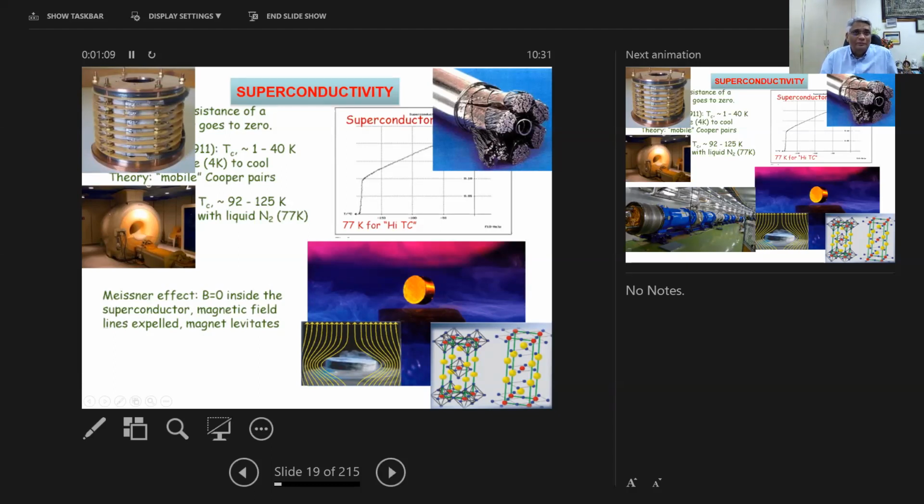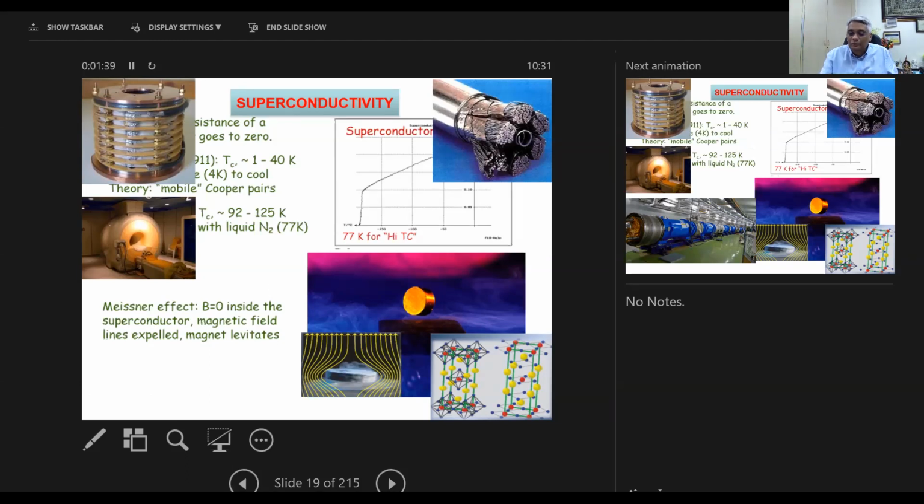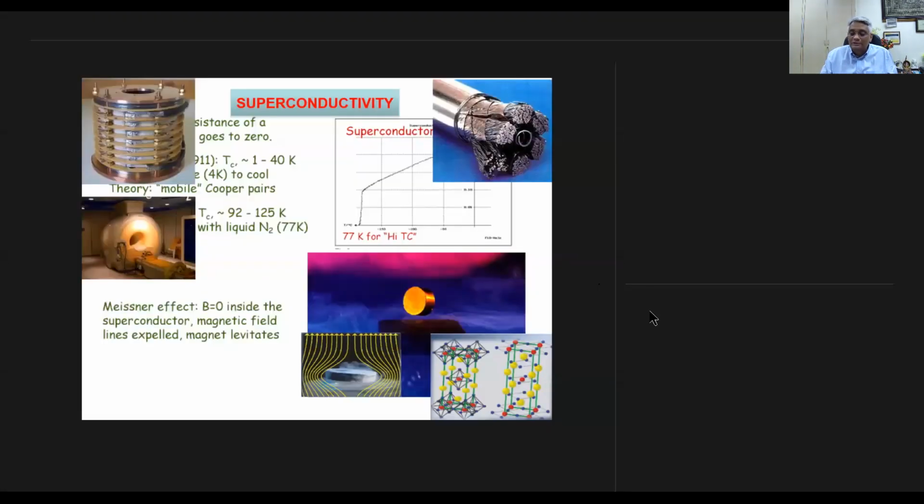But when I'm talking about 4 Tesla of magnetic field, I'm not talking about an electromagnet anymore, because there the limit is just 3 Tesla. That's where superconducting magnets are required. You see, the beauty about these superconducting magnets is, if you take a bunch of those superconducting wires and wind them into the form of a coil, right? I said to get a 3 Tesla electromagnet, you need a huge coil, and through this coil, you're passing a large amount of current.